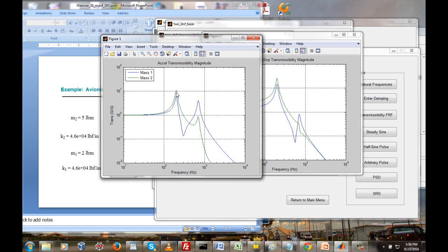But do you remember that half-power bandwidth method? If we were to apply the half-power bandwidth method on either of those two peaks, that should come out to be 5% damping, which corresponds to Q equal to 10. And you can see for this second mode, both of those peaks fall short of the 10 value, but they both correspond to Q equal to 10, or 5% damping.